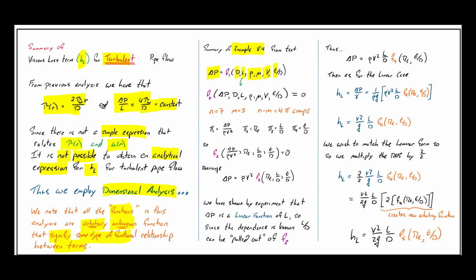So it's epsilon over D. The epsilon value is literally the height, or the measurement of the average surface roughness. You can take a look in the book, but epsilon has a value of length, and D, the diameter, is also a length. So now that's the functional form, and that gives the value of f1.